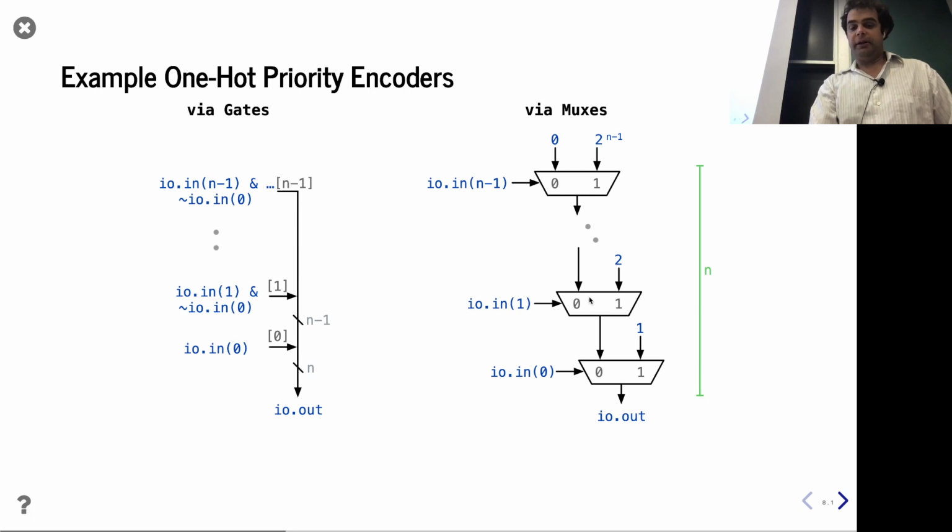Cool. So this is the mux approach. It's cascaded muxes. Alternatively, we can concatenate wires together. You can see, bit by bit, for example, if it's this one, which is the highest priority, right? Well, if that wire is one, then it's going to win.